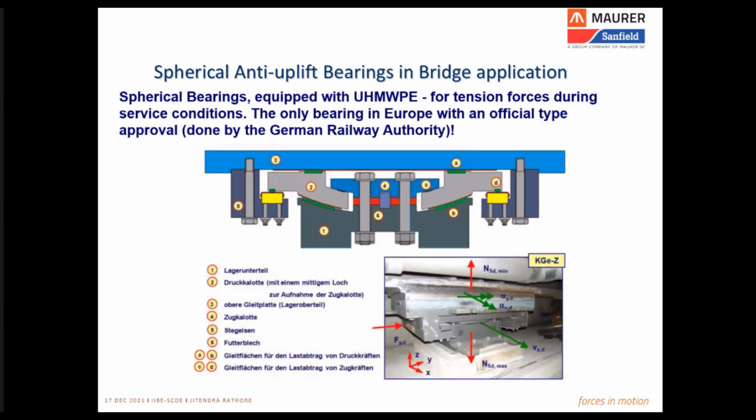And the earthquake may come maybe once in a 10, 20 or 50 year lifespan, or it may even never come in the entire life of the bridge. So for a seismic uplift, the design is not that challenging, and we as bearing designers can get away with providing some simple lateral clamps.